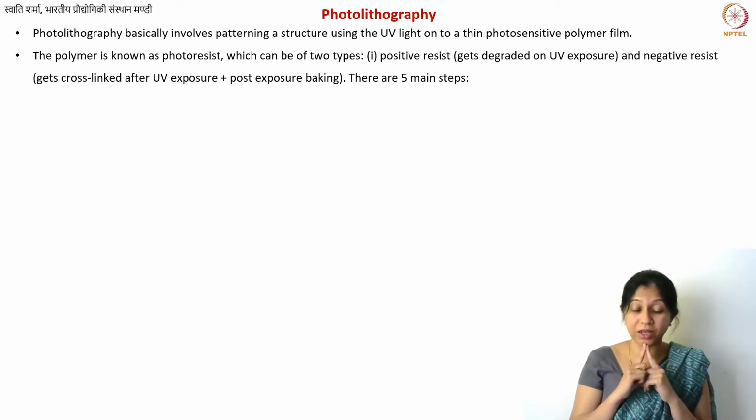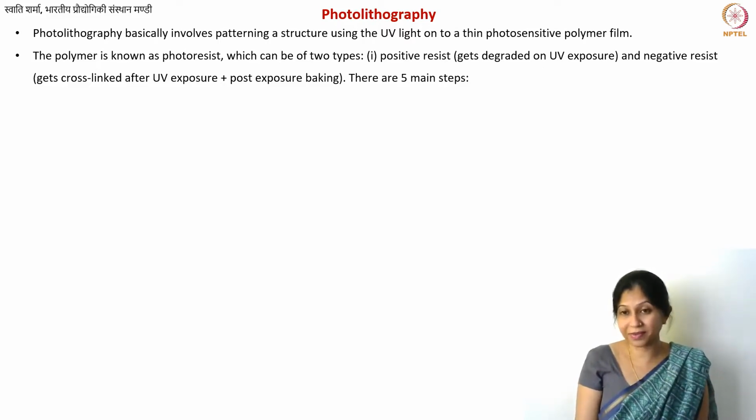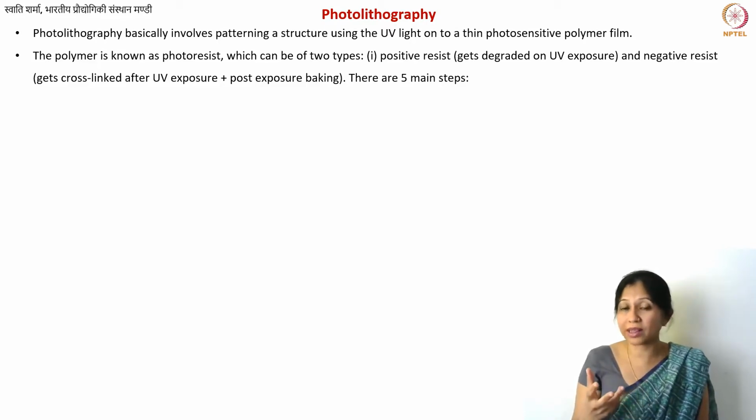Now photosensitive materials may be sensitive to different wavelengths of light. All materials do not have the absorbance at the same wavelength. Now, in the case of photolithography, we are particularly using the materials that are sensitive to UV light. And these materials are known as photoresists, or commonly you just call them resist.